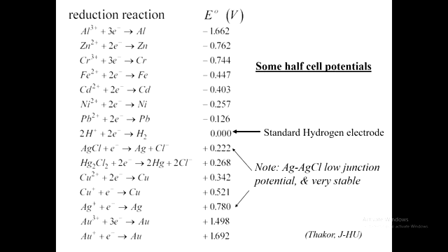And you might say to me, well, okay, it's a differential amplifier, so if we've got 2.2 volts on the other electrode, won't it cancel out? And the answer is, well, yes, but whereabouts does it get cancelled out? It might be outside the operating range of the instrumentation amplifier to do that subtraction with that small voltage present being amplified internally before it's subtracted. So we need to take care with that.